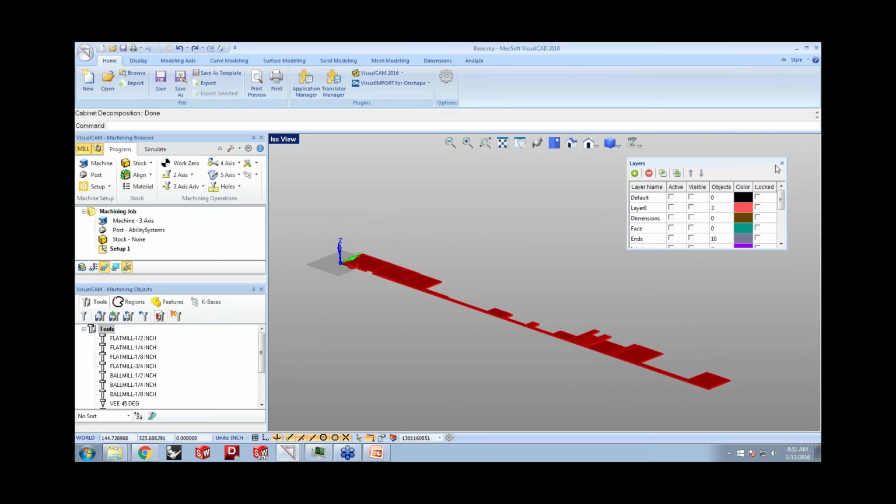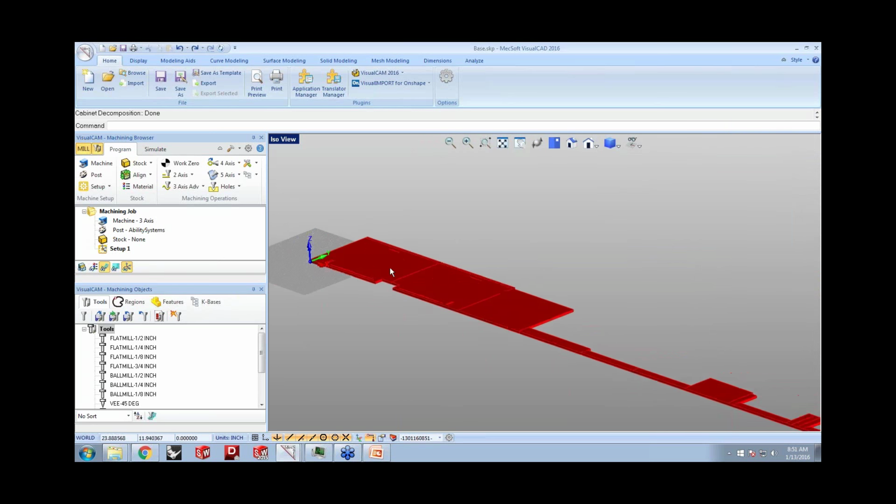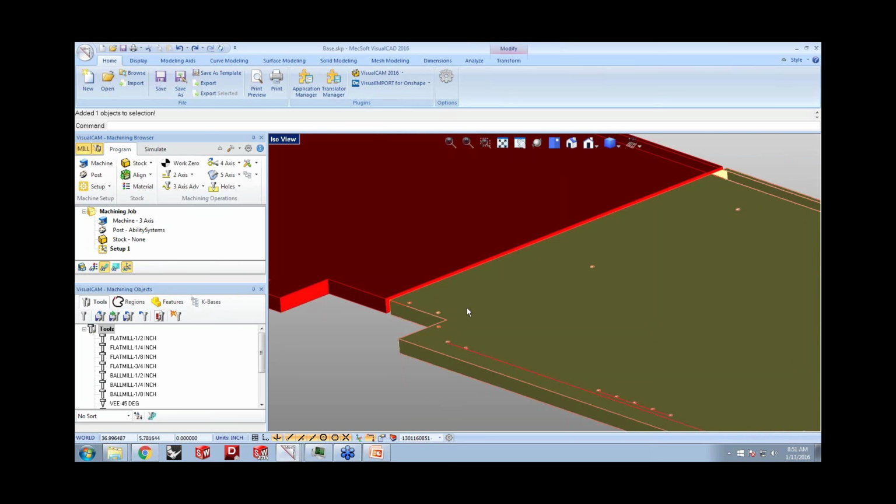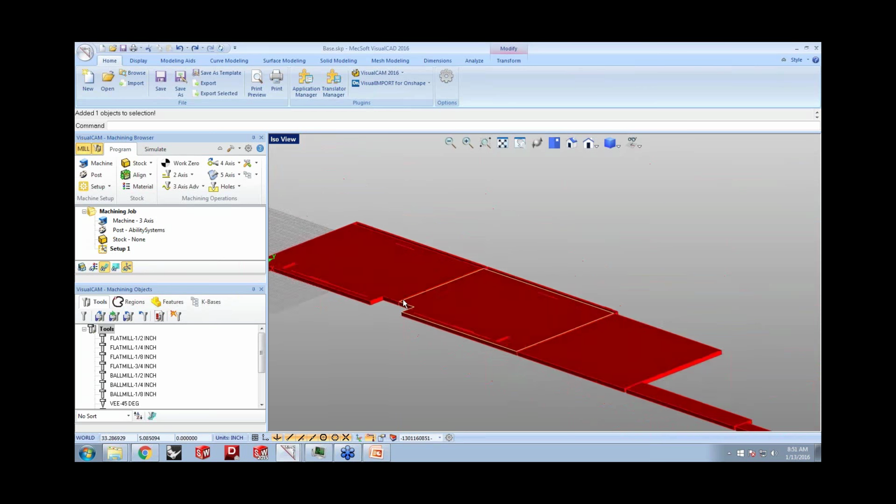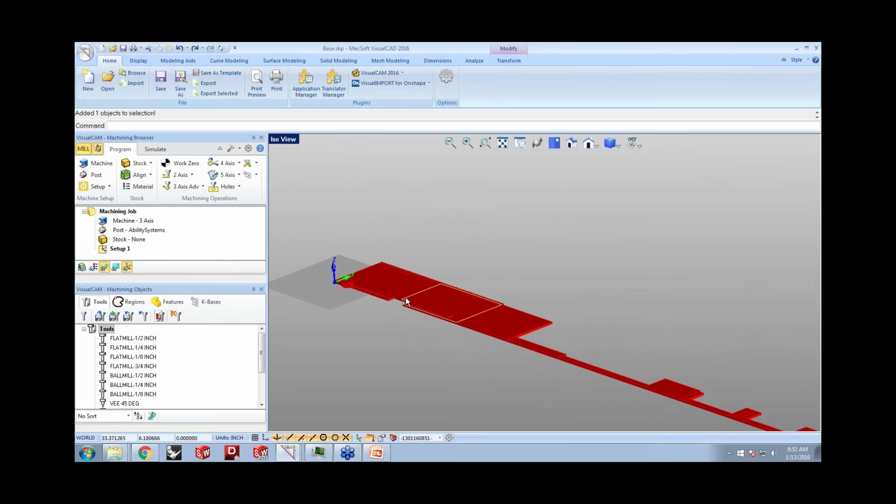So now we have this model in here, which has all the flat panels, and you can see it has both the mesh geometry, the curve geometry, and also the curves for each of these. Now, you may have to do a couple of steps in here to clean up, to basically just retain the curve geometries in here so you can nest them into a sheet.